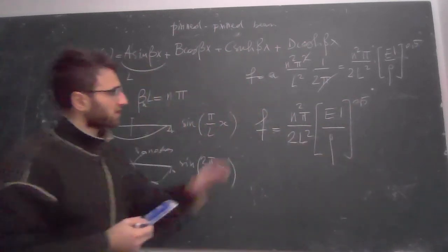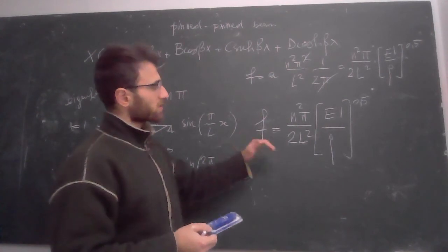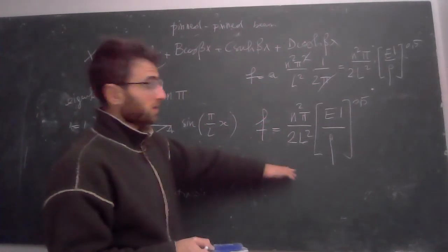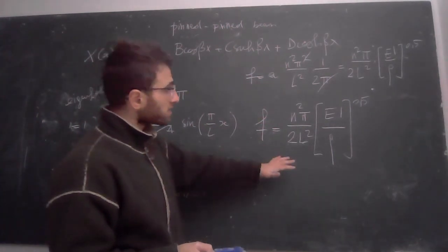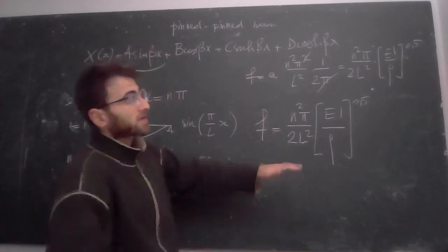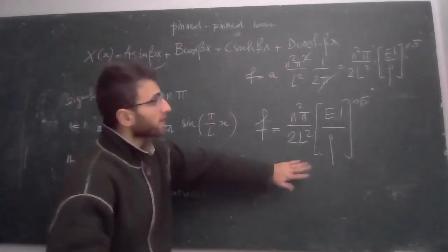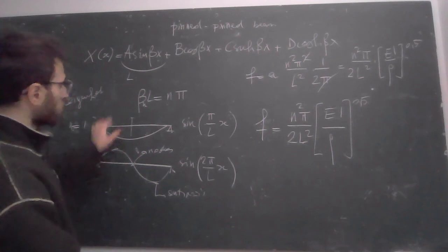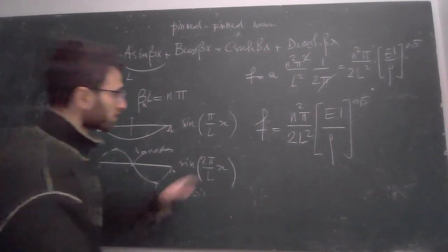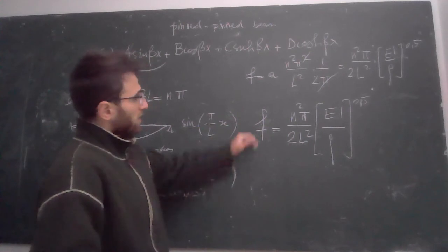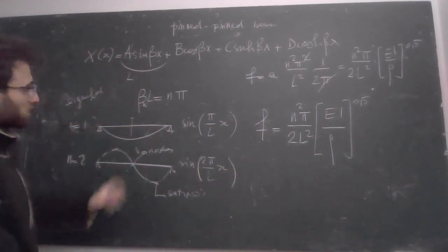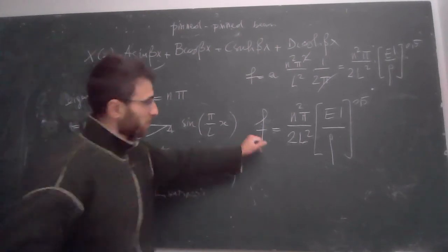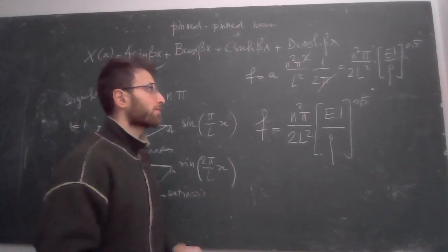This is the expression of the frequency of vibration of a simply supported beam, of a pinned beam. Very important. We will find in the standards, for instance, if we want to study the vibration of floors, this equation. So these are the mode shapes, and these are the corresponding natural frequencies of these mode shapes. Very important expression that we derived here.